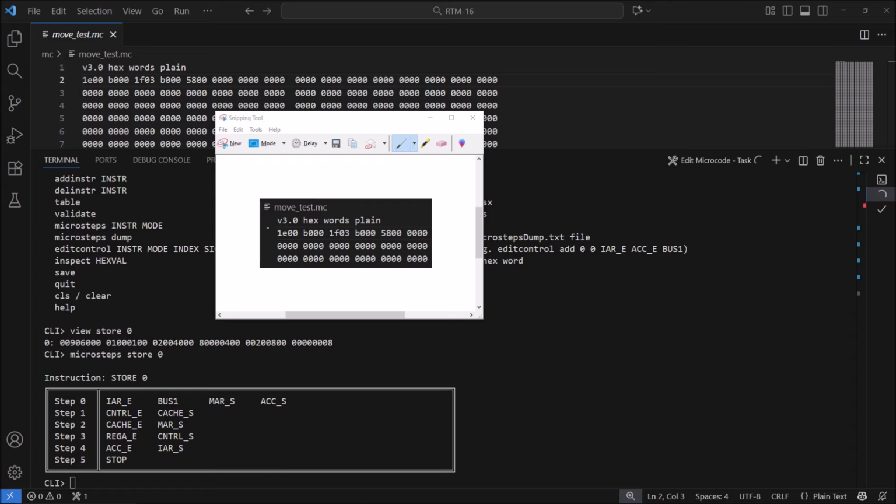So these 2 points here are memory locations. Now within the memory location we've got the actual opcode, and within this memory location we've got this B000. But the B000 refers to another memory location. It tells us where we want to store the contents of register R0.